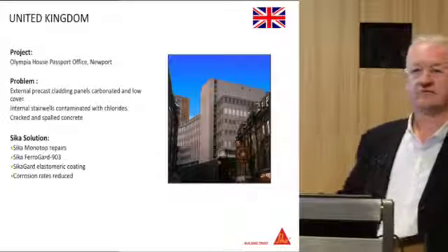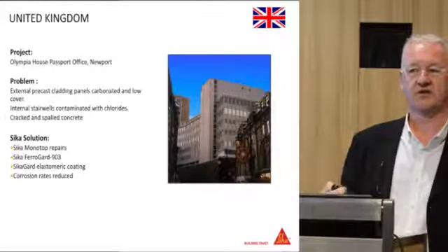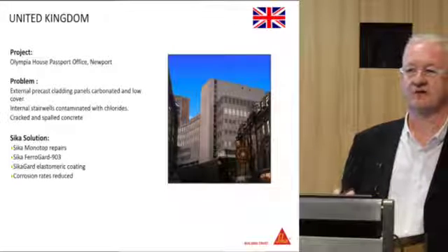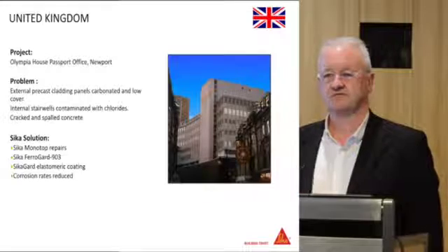What we can't do with inhibitors is stop corrosion, unlike CP, which you can. But what it does is control corrosion to acceptable levels where you probably won't have to do anything for about 10, 15, 20 years.